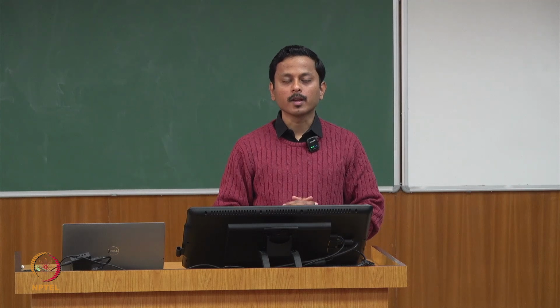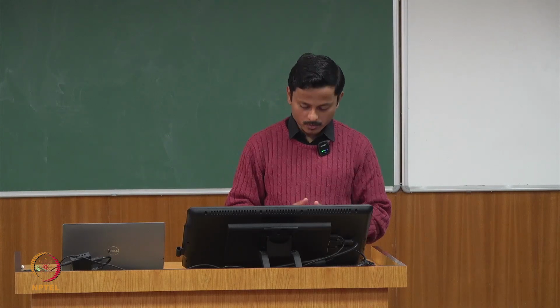In the previous lecture, we were discussing the Boussinesq approximation. We showed how the continuity equation changes to a form which is similar to the incompressibility condition. The Boussinesq approximation again imposes a restriction on the velocity field that it has to be divergence free. And we also saw how the momentum equation changes. We'll start from that momentum equation today.